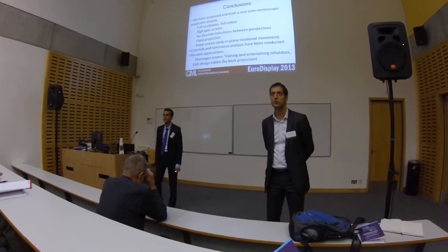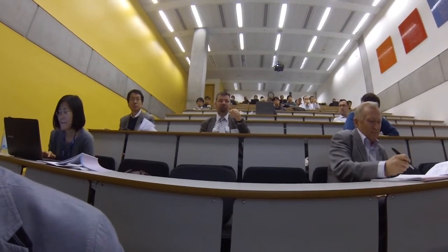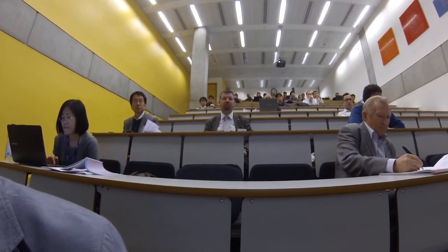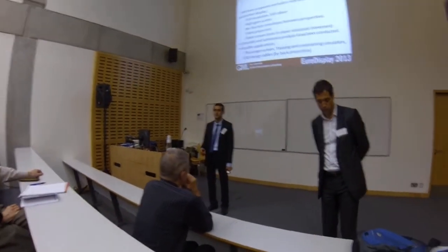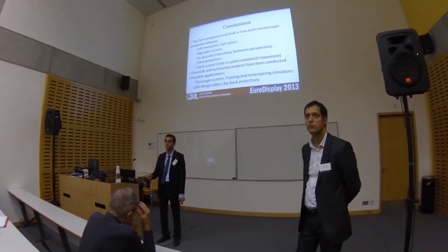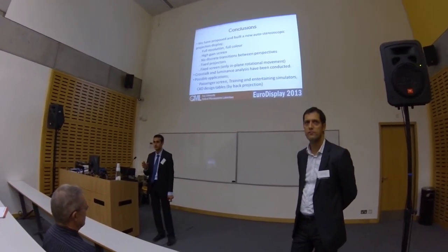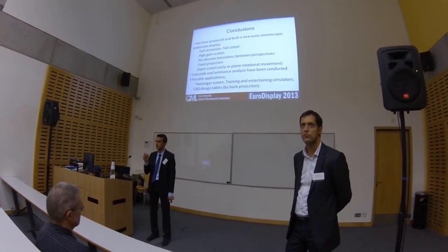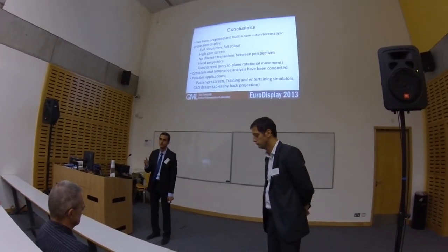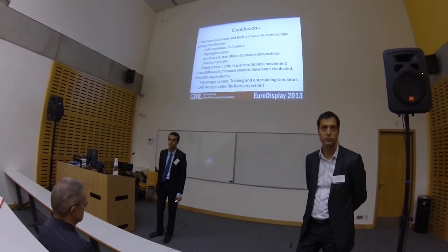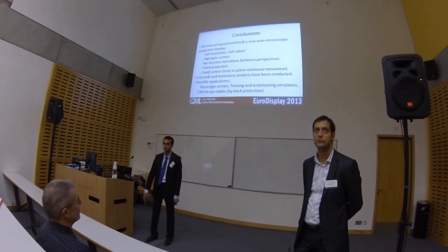Okay. Last question? The actual diffuser material, is that just commercially available? Yeah, that's commercial. We purchased them from Luminit. It's an aperiodic diffuser. We also used a periodic diffuser, but since the retroreflectors are periodic and the diffuser is also periodic, some moire patterns or fringes occur. The periodic diffuser diffuses less in the horizontal axis, or the minor axis, but it produces some moire patterns. That's why we chose the aperiodic diffusers, so that we get rid of the moire patterns.